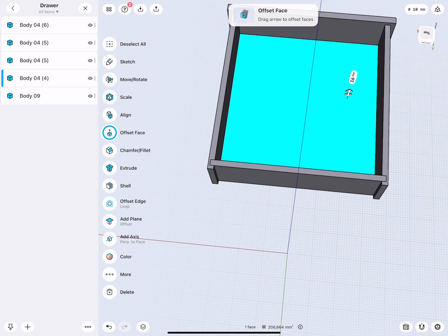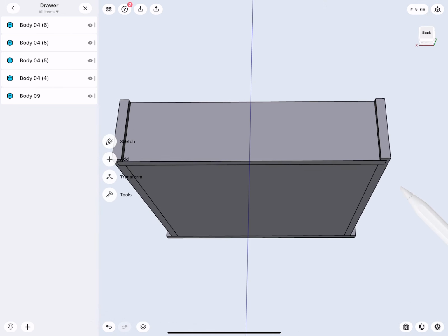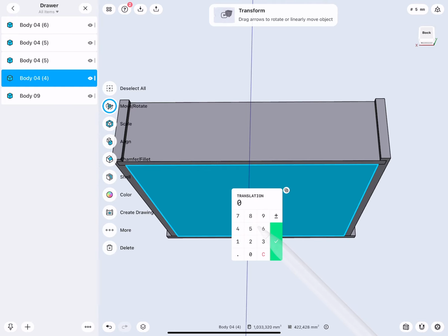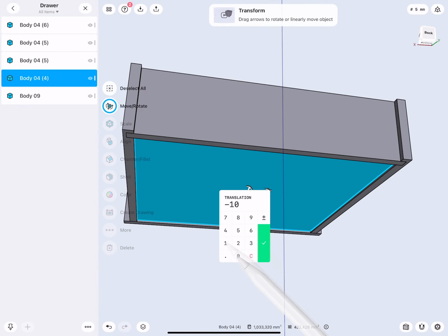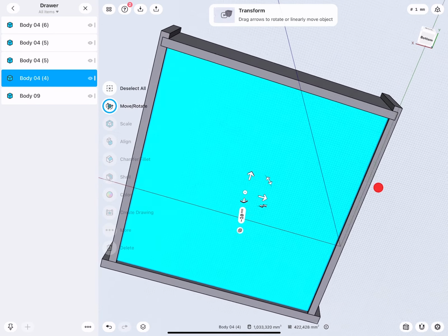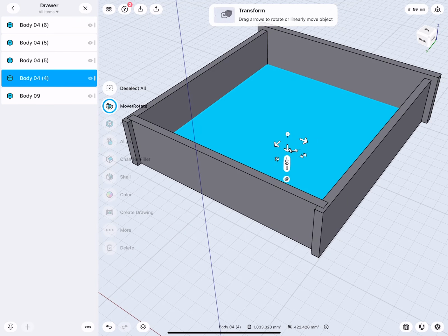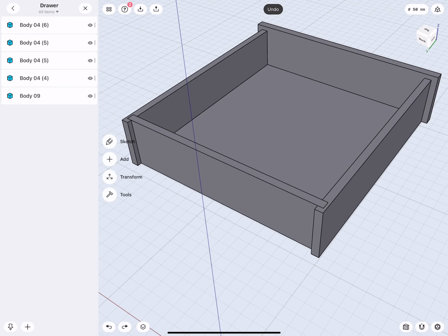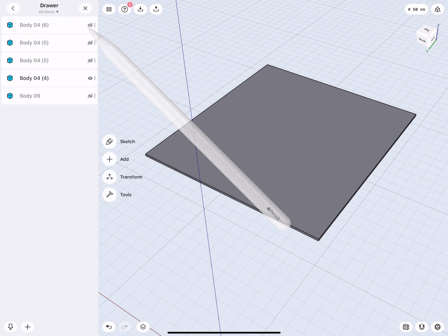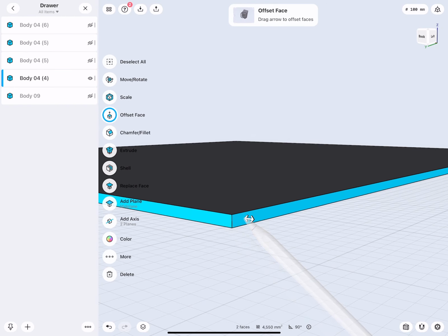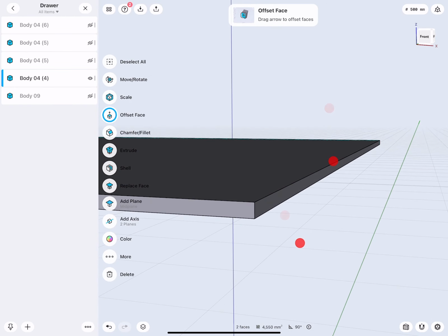Now this can actually be a very thin material. Let's make this 5 millimeters. Very nice. And I would like to have this raised 5 millimeters. Very good. 5 is too small. Let's go 1 centimeter. And I need to cut grooves for this board to sit in, because right now, well, we just fall down. So what I will do is I will hide everything and select all these edges.